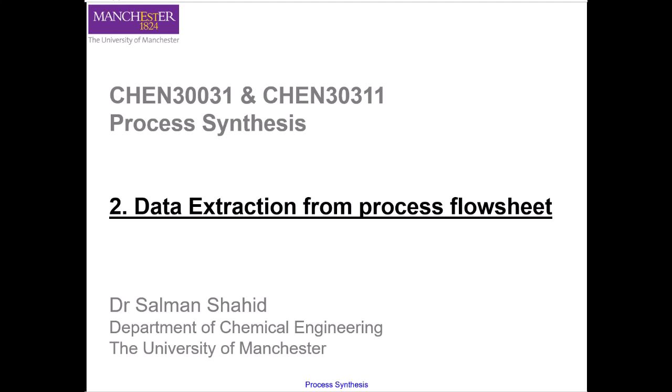of the pinch analysis. So when you performed a design intensive week, you simulated your data, and most of that data for the hot stream and cold stream of your process and the conditions were given to you, and your main goal was to develop, for example, a heat exchanger network to minimize the energy consumption or to maximize the energy recovery. But now you are the design engineer, and it means that you have the power to change those values of temperatures or conditions, and you can also change your process.